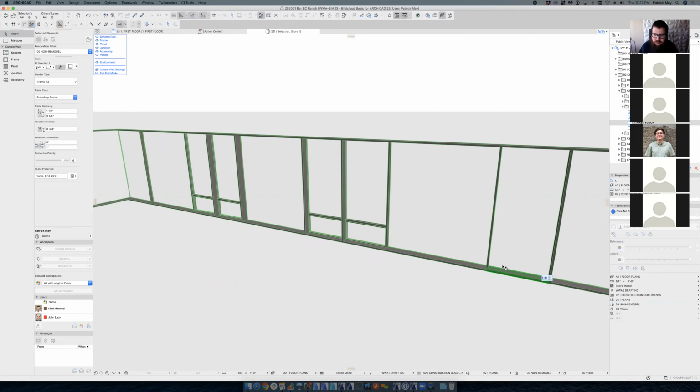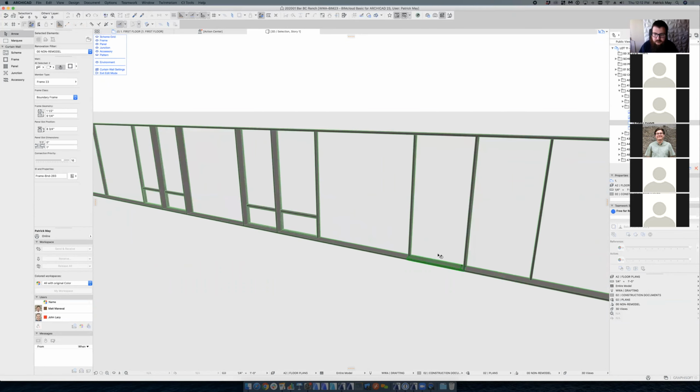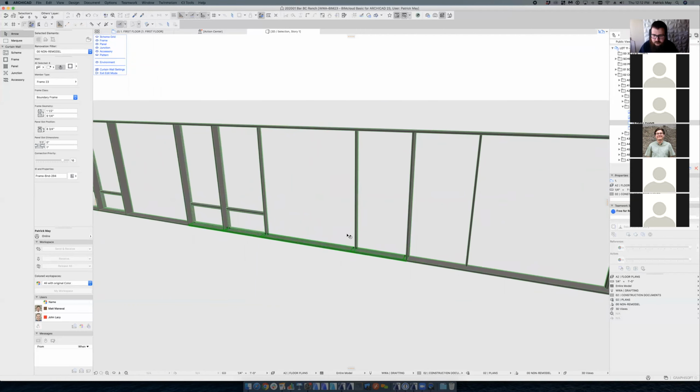So it's pretty flexible, especially even for us when I was in like the early SD stages of designing this out and doing design options every day of different patterns. You don't have to go through the full steps of creating a defined system for it. You can custom model that and change it on the fly. So I liked that part of the curtain wall as well. So something to consider when you're doing early SD modeling.